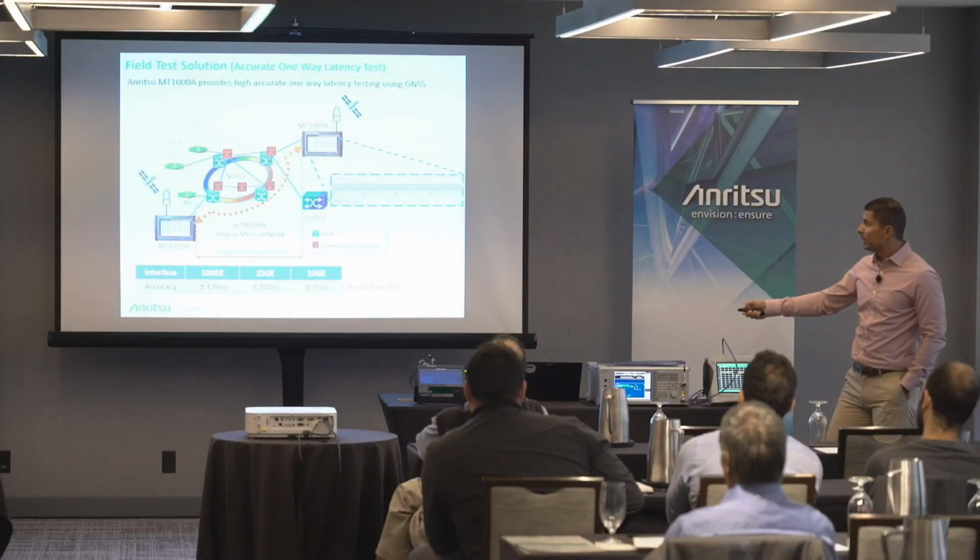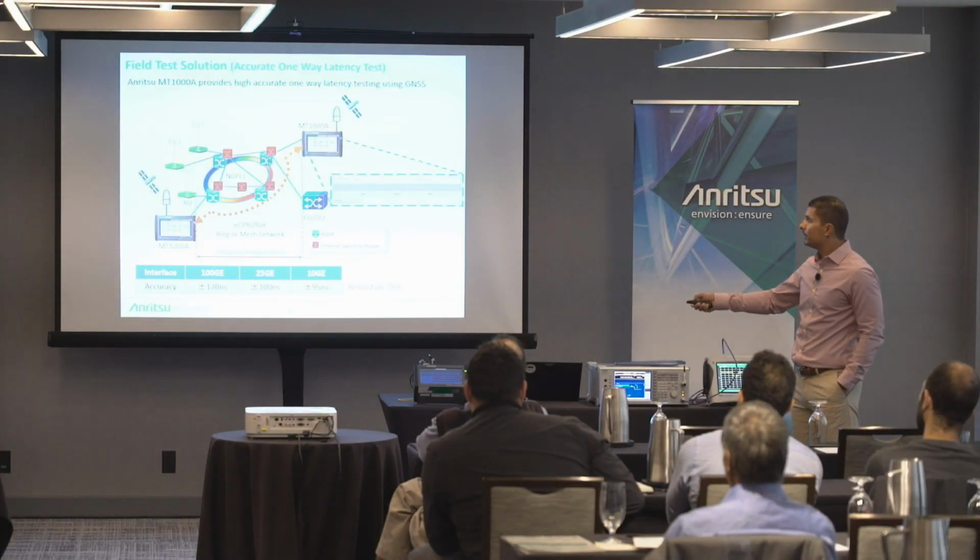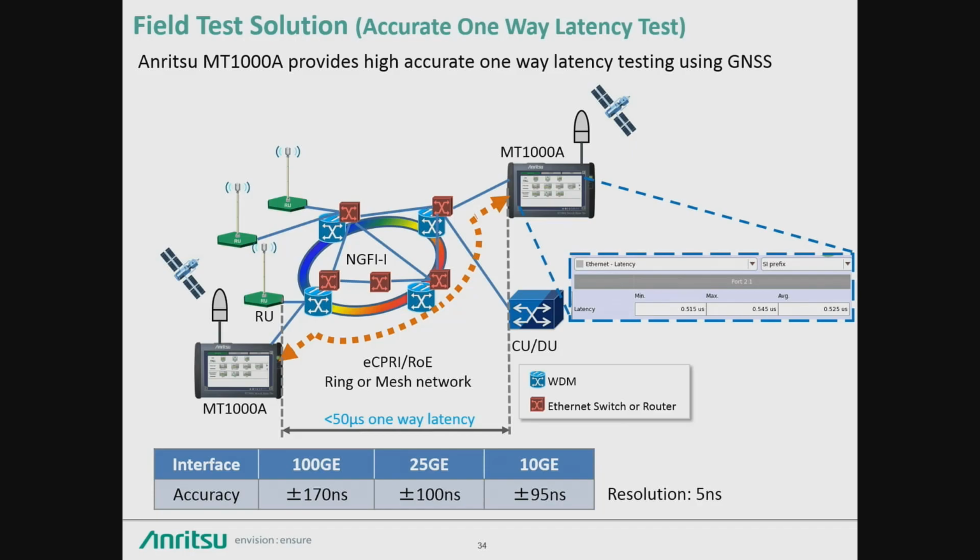So, what does this look like from a physical perspective? You have your MT1000, you have your 2 different network masters. You notice that we have the synchronization here. I have the GPS. Why is that? Because now I can, again, as I mentioned earlier, similar to how I used my application for synchronization, I have the ability to synchronize my tester to that of a known reference. So I have GPS timing on both instruments. This allows my clocks on my testers to be identical to one another.